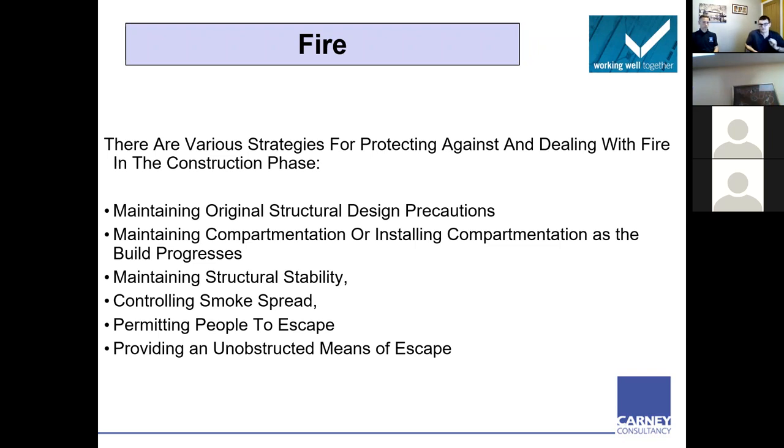It's not a case of decimating all the structural compartmentation of the building by taking all 20 off and then starting to put them on one by one. No ifs, no buts, that could not happen. And also reiterating to the joiner, if you go to put that new door on and it doesn't fit, it's not right, that old one goes back on at the end of the day. For overnight, no ifs, no buts, it's not just left out. It was being critically clear with them at the very start of the project that this is how it had to be done.